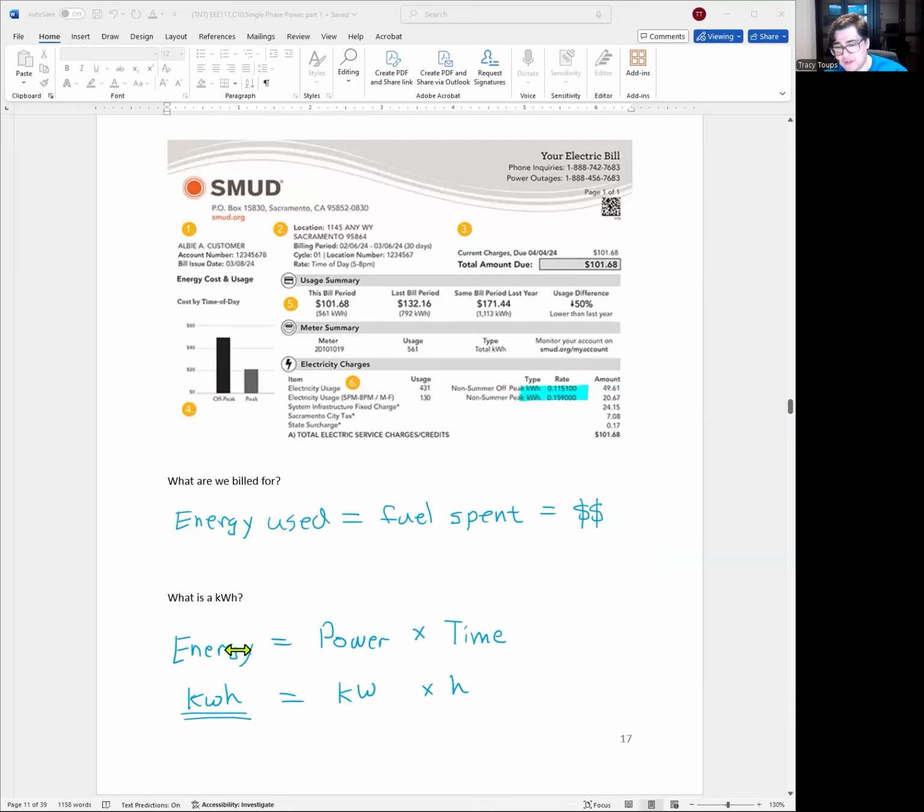What's the unit of energy? Kilowatt hours. Where do we get kilowatt hours? Remember, energy is always power multiplied by time. Power is the rate of energy used per hour. You multiply by the time, how many hours you use. So if you're running something for 8 hours a day, you multiply power times 8. Our total is going to be kilowatts times an hour. So 1 kilowatt hour.